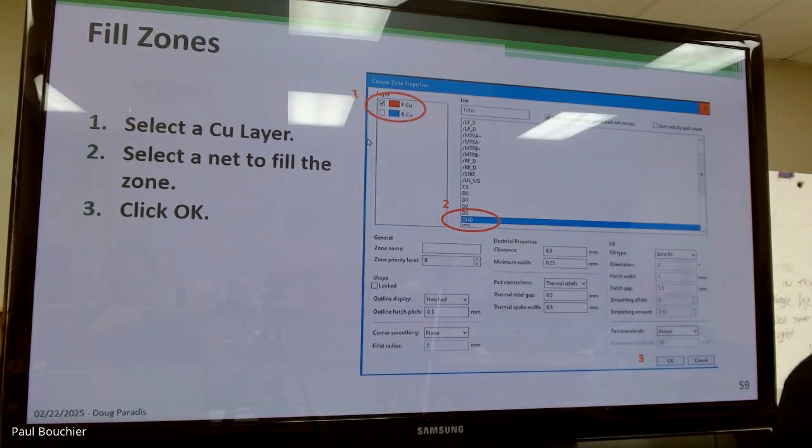Okay. Select the edge fill zone boundaries. Is this your good copy? Yes. Okay, well, you can always download this again. So go ahead and select the fill zone boundaries, and then use the delete tool, or just hit delete. That deleted one of the fills. I think it's got two of them, one on each side. Which one did you delete? The first one. Okay, well, delete them both, the red one, the top side, and then the bottom side. Yeah, delete. Okay, so they're both gone.